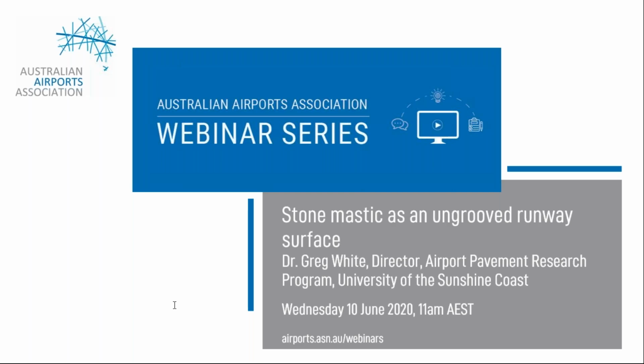Okay. Given SMA is not porous, in a deluge, what is the difference in drainage capacity on an SMA non-grooved or a grooved runway surface, and how does that impact friction in that situation? Yeah, so that's really the same question, just asked in a different way. Again, we've still got minimum and maximum crossfalls on runways for overall drainage. The function of your grooves and the function of the 1 millimeter surface texture in SMA isn't about overall drainage. It's about localized escape paths between the tyre and the pavement surface.